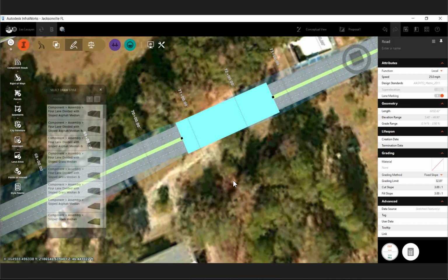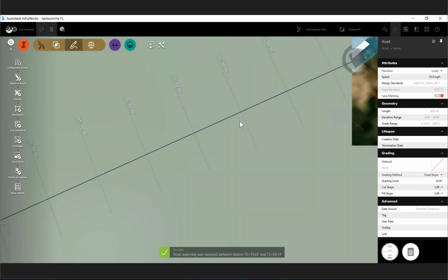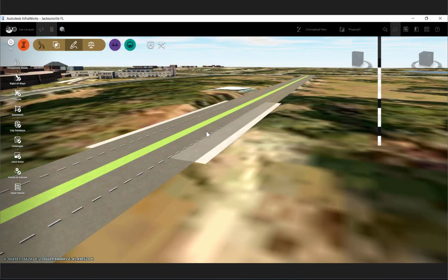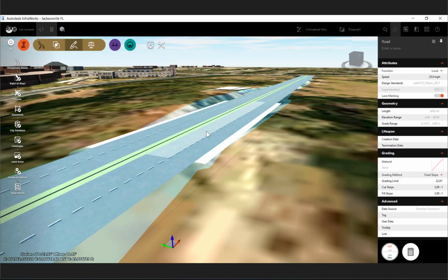This used to be all controlled via Autodesk, the styles that we have here, but now they're referred to as components, because when I take this information and push it onto Civil 3D, it will help me. Yes, I can easily pull this alignment and profile into Civil, but go one step further and create assemblies and corridors inside of the Civil 3D software. So that's just a really quick layout of roadway geometry and how I can stylize that roadway geometry.